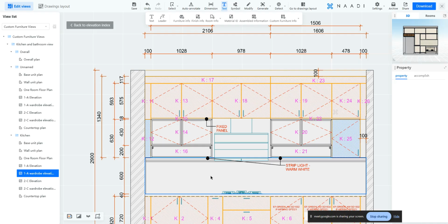Yes, that eventually leads to another important thing, which is your micro selection. Okay, so if you select any component here, it will select that entire component. If you select the shutter, it will select the shutter altogether. But if you want to select only a specific component in that cabinet, then remember here in 2D, I'm telling you, remember the shortcut is Control Shift 1. This is a one-time toggle which needs to be done. Okay, for a project, for a single time. Once you refresh this and again you get inside the same drawing, you have to do it again. Okay, so remember the shortcut, it is Control Shift and 1.